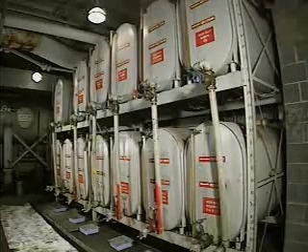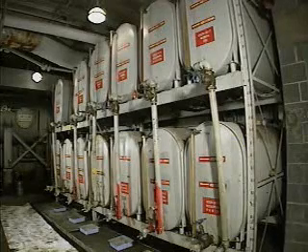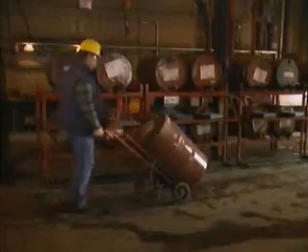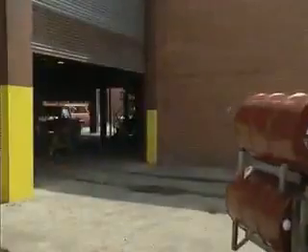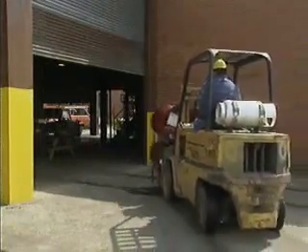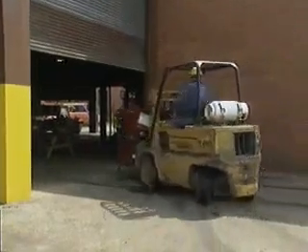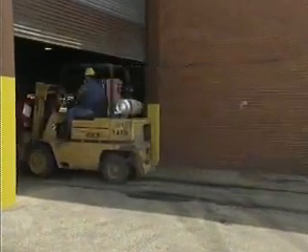In this part, we'll talk about some standard procedures and precautions that are associated with handling and dispensing lubricants. Generally, when a lubricant is needed in a facility, workers move the lubricant containers from bulk storage to a central location in the facility where the lubricant can be dispensed. If a lubricant is taken from outside storage in cold weather, it should be allowed to warm up indoors before it's used. Low temperatures can thicken lubricants and make them unusable until they've been thoroughly warmed.